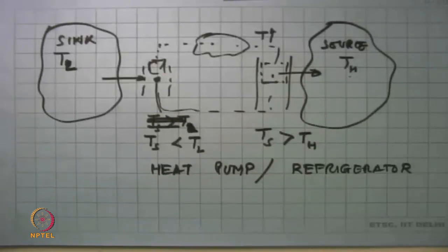Does a high temperature H2O2 fuel cell have a chance of explosion? Okay, there's a question that if the hydrogen oxygen fuel cell is run at a high temperature, is there a probability of an explosion? So mostly the hydrogen oxygen fuel cells are being run at low temperatures. There are some which are run at high temperatures, but then you have to design it so that first it doesn't leak, and you are able to do thermal management of that. And yes, there is always a remote chance that it can explode. Much like if you ask the question, traveling in an aeroplane, is it possible that the engine will catch fire? And yes, there is a finite probability the engine could catch fire.